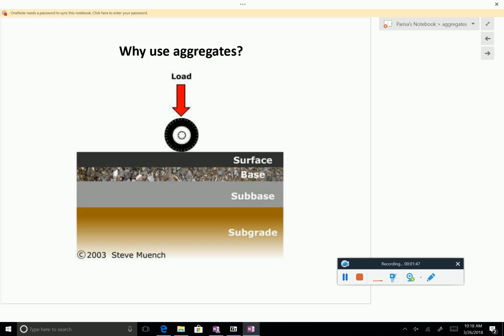If you had a way to see inside the pavement system, it would look something like that. Let's say if you have asphalt concrete, or if you have concrete on the top, what you see is only one relatively very thin layer. Underneath you have base, sub-base, and subgrade.